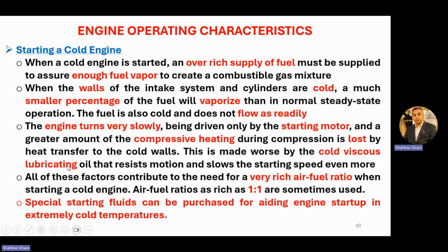So the body is cold, the fuel is cold, the oil is also cold, and the water inside the cooling chamber is also cold. So everything is cold. This is made worse by cold viscous lubricating oil that resists motion and slows the starting speed even more. All of these factors contribute to a need for a very rich air-fuel ratio when starting a cold engine. An air-fuel ratio as rich as 1:1 is sometimes used.